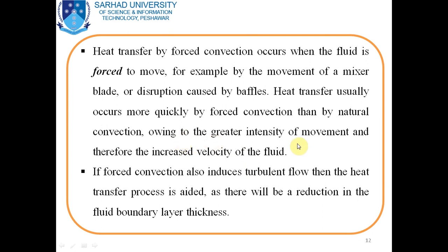That's owing to the greater intensity of the molecular movement and therefore the increased velocity of the fluid. Remember that the word fluid here is used for liquids and gases. Forced convection also induces turbulent flow. Then the heat transfer process is further accelerated, as there is a reduction in the fluid boundary layer thickness.